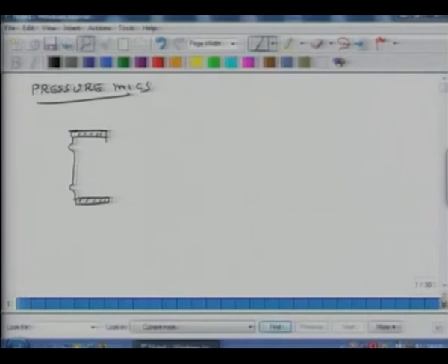On the back side of the microphone, now this diaphragm could be metallic, or it does not have to be metallic. It's a thin film. On the back side, I have a perforated surface. The diaphragm and the back perforated surface are there electrically, and then I seal this entire thing. Also, I have a small orifice here, which is in green. So I have the diaphragm, which is member A. I have a perforated screen, which is member B. Everything is in an enclosed cavity, and I have a small orifice.